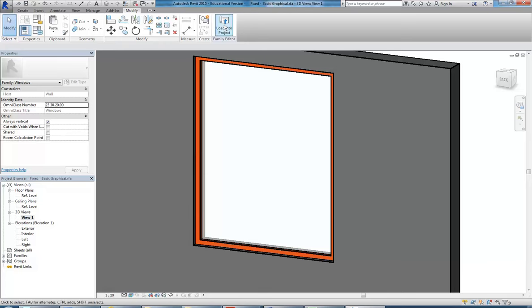And then I can have a look at the values for the transoms. So we've got transom height 1. Needs to come up maybe 2200 or something like that. And a good trick there is just to change it and click apply. Sometimes it works, sometimes it doesn't. Let's see, so transom 1 height maybe, let's try 3,000. There we go, pretty good guess.